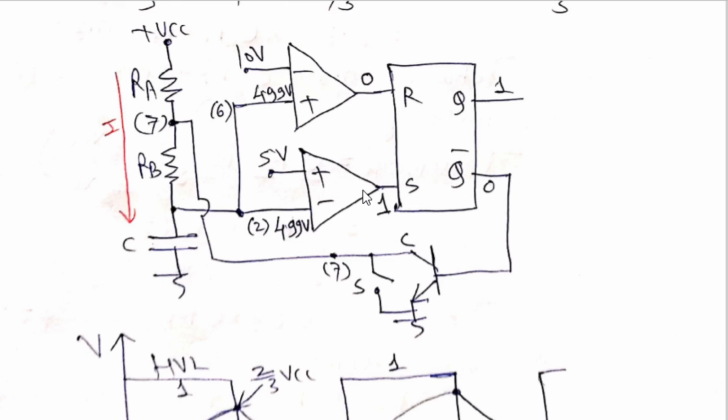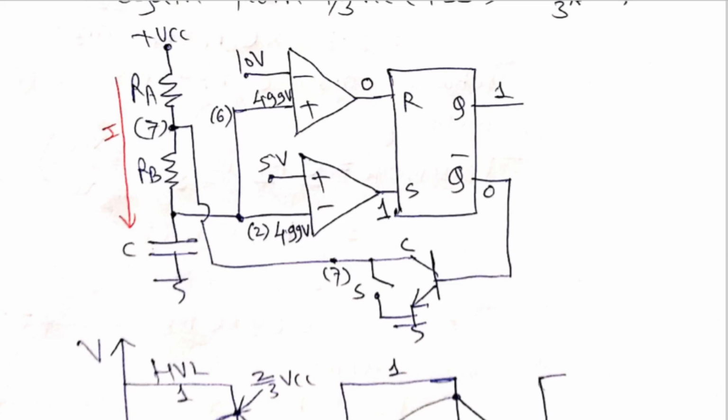And this is our previous condition, the first condition, when we started in the beginning by turning on the power supply. So S is 1, therefore now Q will be 1. And in this way, the output of the flip-flop will again come back to the logic 1. So here what I have tried to explain to you is how long the logic 0 remains there.